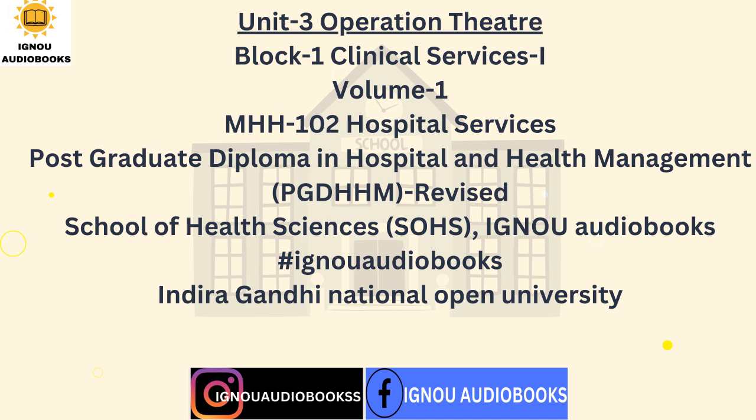Location of operation theatre or suite in the hospital building needs detailed consideration. It should satisfy the following basic conditions in the overall layout of the hospital. The principles of locating operation theatres are: 1. Quiet area located to provide isolation from mainstream of common corridor and traffic in terms of staff, supply, and visitors. 2. Should get least exposed to any source of direct contamination of dirt or microbe.